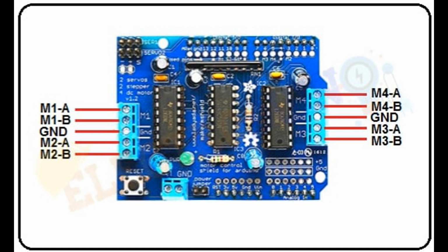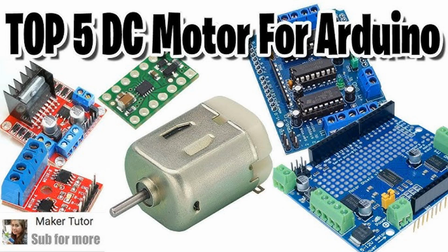Advantages: simplifies wiring and installation. These systems often come pre-calibrated and may include diagnostic tools and safety features, making them ideal for space-constrained applications. Applications: used in automated machines, robotic arms, and other applications where space is limited and ease of installation is essential. Examples: Leadshine integrated servo motors, iDrive by Intelligent Motion Systems. 7.